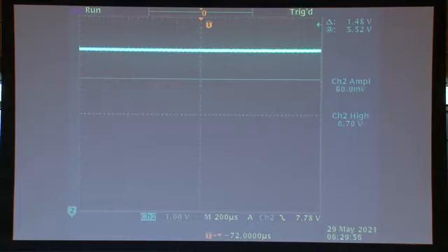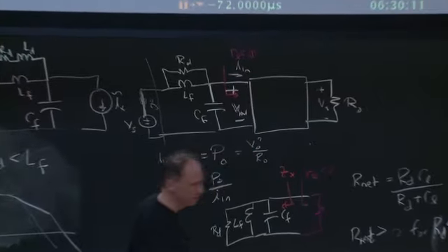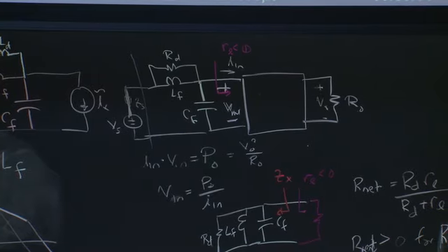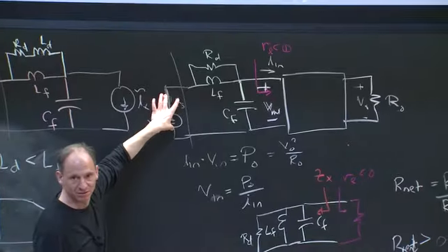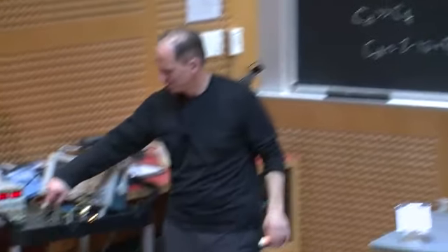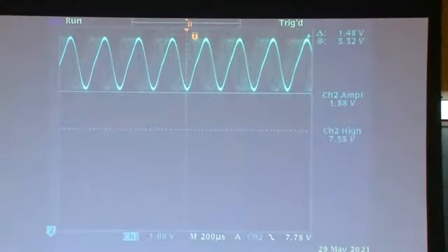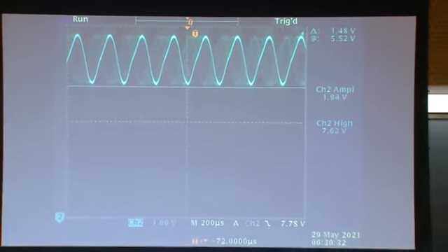that's the input voltage to the converter. So it's exactly the voltage V in here that we're seeing, right? This is the input voltage that we're looking at, V in, okay? If we have the filter in place, V in basically sits at Vs. But if I take out that damping leg, that's what happens. The input voltage is still fixed, but this voltage is going crazy, right?